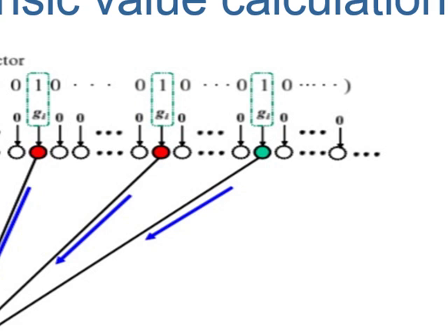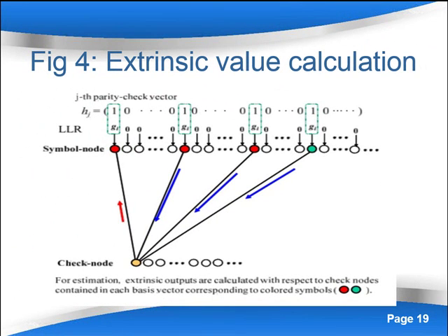From the property of sum product decoding for LDPC code, we can expect that the extrinsic outputs are correctly determined only when the phase sequence is correctly estimated and removed from the received sequence, because the reliability information on channel condition does not match the received bit error attributable to bit flipping occurrence in the SLM method.